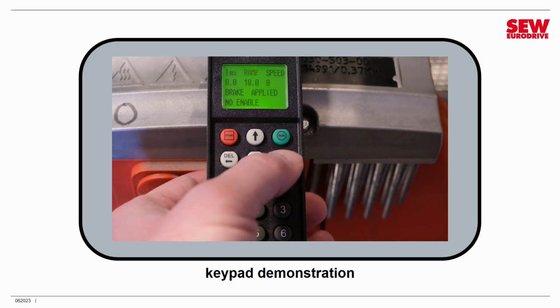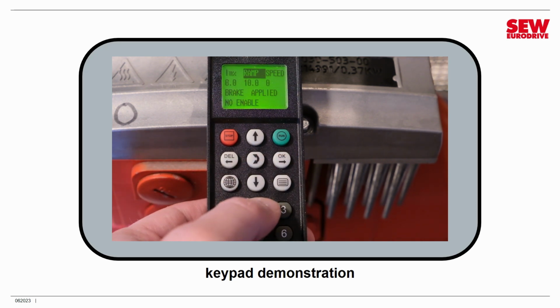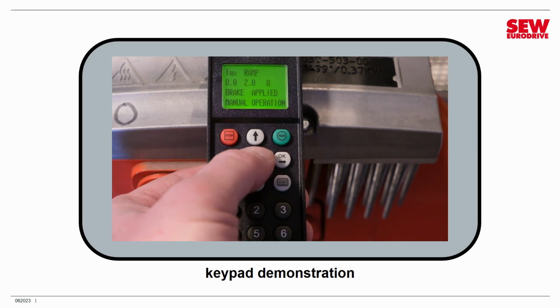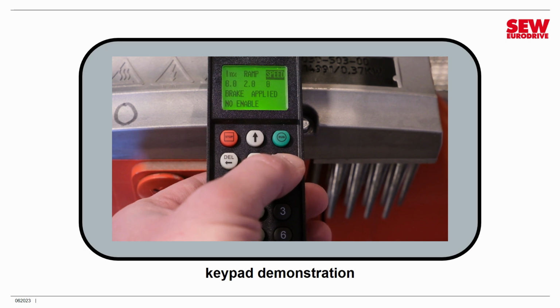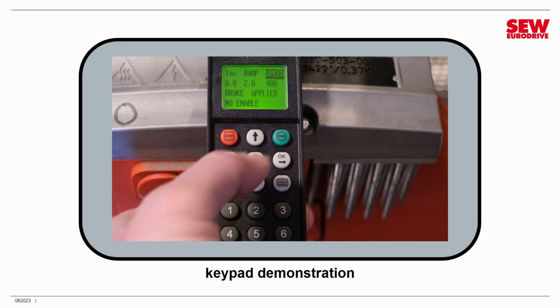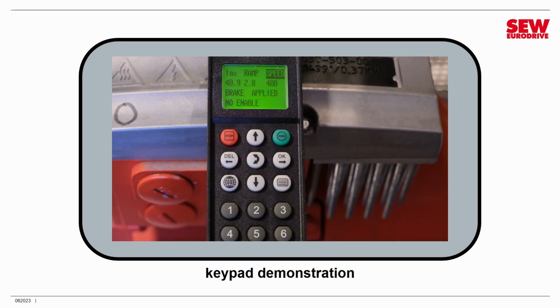It's asking for a ramp. I hit OK to activate that option and I type in 2 and hit OK. And then I have to press the switch button to move to the speed option. And I hit OK again. I'll key in 400 RPM, hit OK, and now press the green run button. And the drive is running.